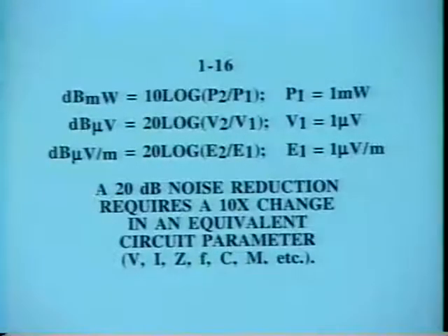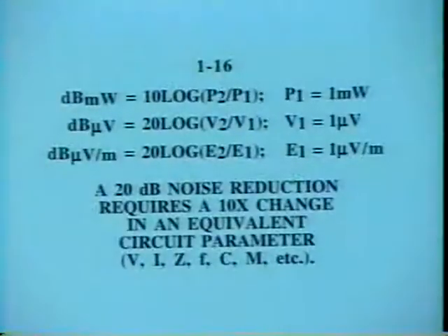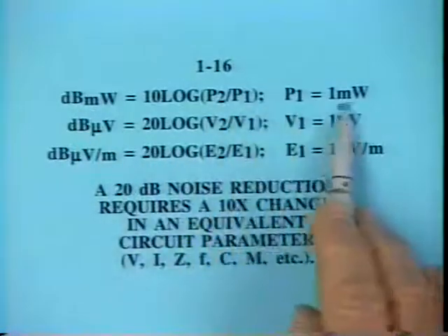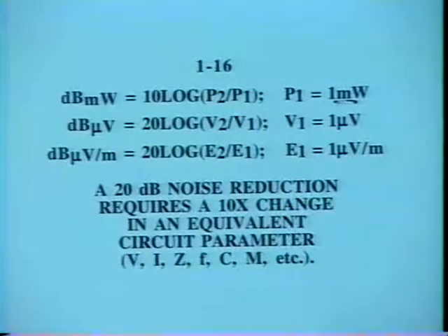All right, well, we'll switch over to another topic for a few moments. We'll talk a little bit about decibels. This is a confusing idea for some people, and we'll see if we can straighten it out a little bit here. The decibel started out as the ratio of 2 power levels, and it had a lot to do with how the ear hears sound. But anyway, it starts out as the 10 log of the ratio of 2 powers. You hear people talk about dB milliwatt, or dBm. dB milliwatt would be a power level measured relative to a reference of 1 milliwatt: 10 log of a power relative to a milliwatt.